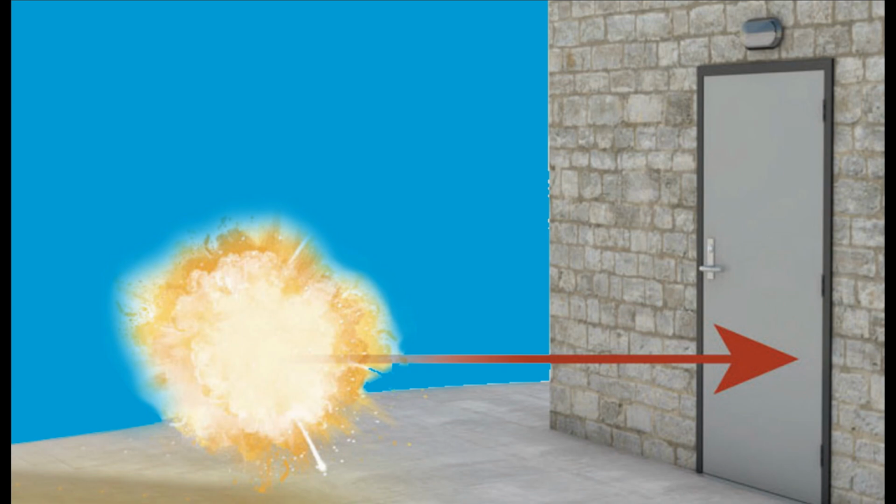Yeah. So people that don't live here in Florida say, why do the doors on your house swing out? Yep. It's a seated position. It's easier to maintain. So that's the condition. Now, if you're in a hurricane zone, hurricane resistance is different than blast resistance. Hurricane testing, although it's a pressure, say 60 PSF, also has 2x4s thrown at it. It's pulsating positive and negative pressures. It's not the same.